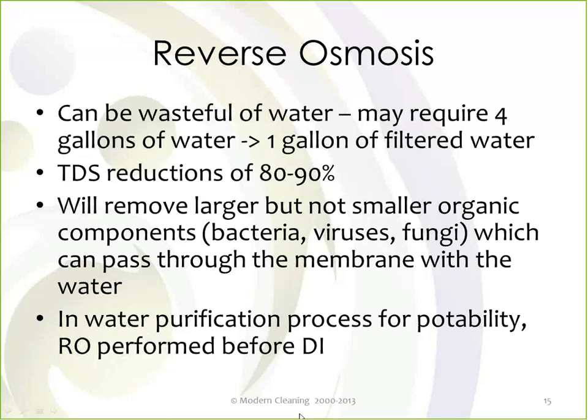And so you do have some type of sanitation if it's going to be drinkable water. And again, it's usually put before the deionization part of the purification process if you're going to pair 2 processes, because you're using large quantities of DI water. They often do that to extend the life of the DI filters.